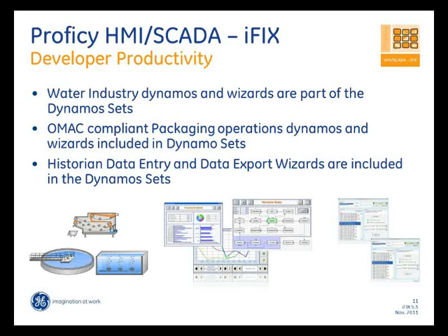The other two capabilities that we also added in iFix 5.5 were what we call the Historian Data Entry Wizard and a Data Export Wizard. So with Historian Data Entry, you can actually do manual data entry directly into Historian using a timestamp and a value. So any lab data that you want to enter, or any manual data that an operator might have collected across his plant, he can at his leisure go in and enter the value using the timestamp of the value recorded, and it goes right into Historian at the timestamp that the operator or the supervisor might have specified.